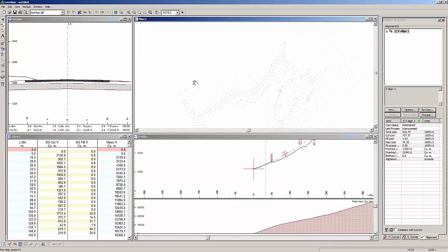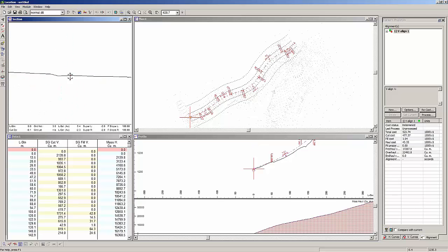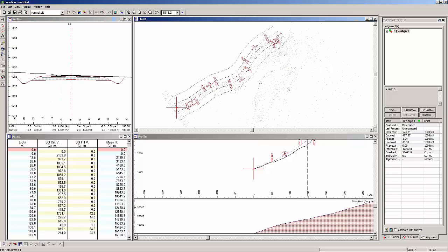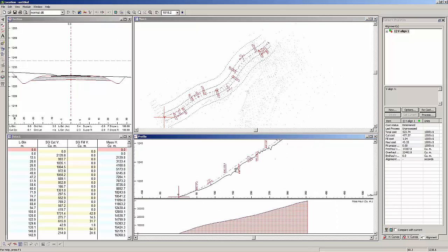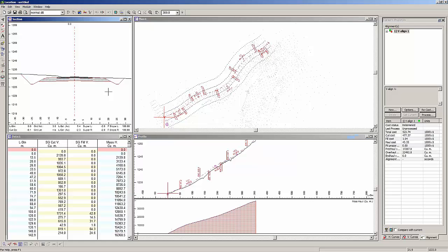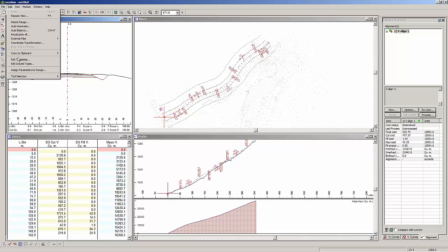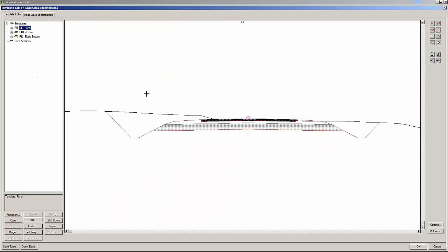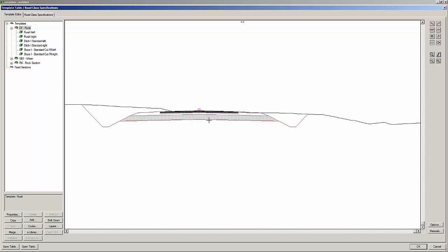And there it is. Our default template in RoadEng was set up as such, and here is the alignment now. It's come in, same surface, same horizontal vertical alignment, but we've chosen a RoadEng cross section and applied it to it. Of course, you can change the RoadEng cross section. It's very similar to assemblies and so on in Civil 3D.